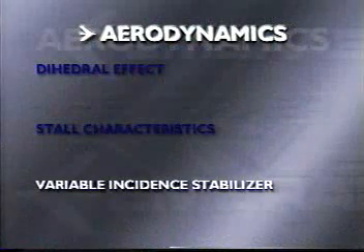The variable incidence stabilizer. There is one other important feature of flying faster I would like to point out. On a fixed-tail aircraft, flying at low speeds, the elevator needs to be commanded up, while flying at higher speeds, it needs to be commanded down.